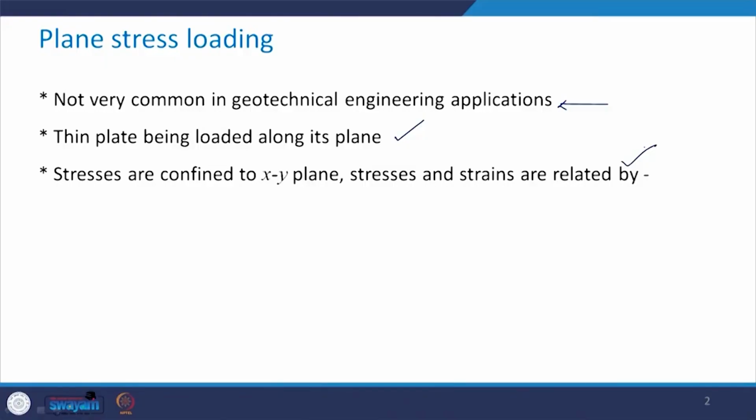However, sigma z was non-zero. So, here in this case, this is related to stresses which are confined to xy plane. So, let us see how the stresses and strains are related in this plane stress loading case.